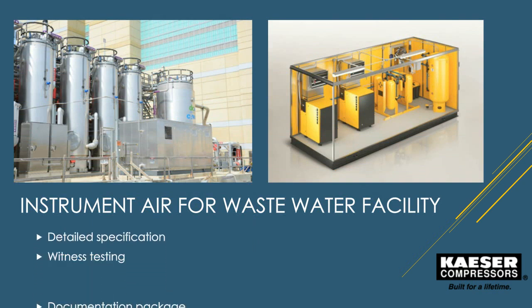Here's another example, which was an instrument air package for a wastewater treatment plant. It had a very detailed specification. You can see the exterior is standard aluminum skin, unpainted per spec, and it had a wide variety of controls within. It also had the ability to have witness testing. Therefore, the customer could validate and verify that the package that they purchased was built to spec. And of course, documentation.